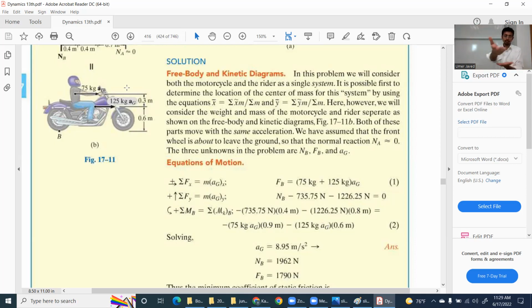And I always have, even in my notes, I have told you, summation of moment about point A is equal to, in a pure translation, the IG alpha, the alpha will go to 0, plus MAGD. Last semester, when I gave exactly this problem, 80% of the class did not write MAGD. Again, something to think about, something to revise.